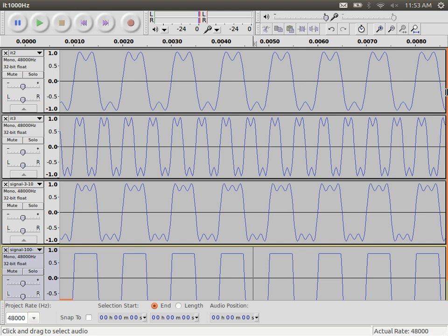That's what was received. Then the receiver, okay, on average, is it high here or low? Okay, there's some low parts, some high parts. It turns out it's low on average in this period, bit 0. Here, it's low on average, that's below the level, bit 0. That would represent a bit error in our transmission.